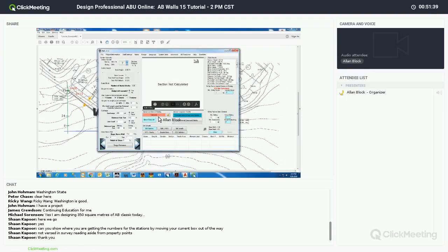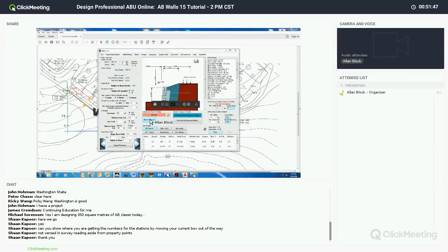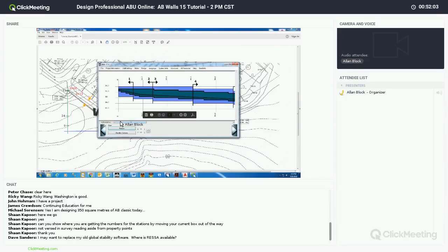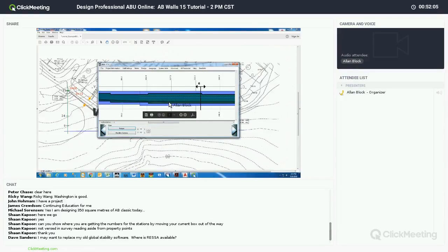And now, instead of using calculate, I'm going to hit the match grids left button, which is going to keep the grids on the same coursing from section to section. And if you ever are curious if you've hit the match grids versus calculate, you can always just go and view them again by hitting the big blue arrow to the left. It'll take you back to the panel summary page, but as you scroll through, you'll see the areas where you actually have grid involved. Now, if they jump section, you would notice because the grids will no longer line up when they cross from one panel to the other. All right, big blue arrow to the right.